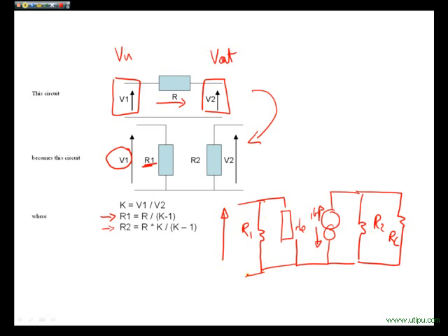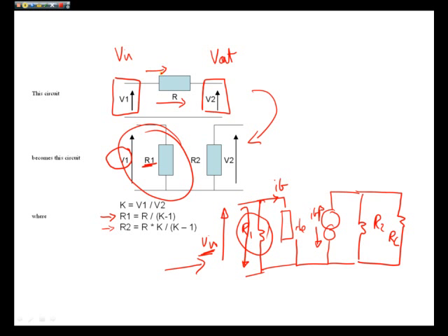Okay, so if we now look at our input signal to our design, V in, this component R1, this Miller component, effectively has no effect when you look in to our V in signal. It still will affect IB into the RBE resistor. What will happen in reality, some of the voltage of V in will cause a current in R1. So that infers that there will be a small current flow into the design.